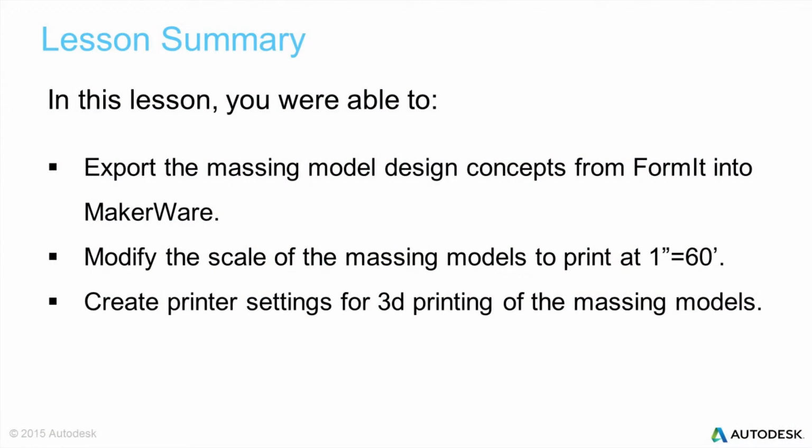So in this video, we learned a couple of key things. We were able to export the massing model design concepts from Format into Makerware. We were able to modify the scale of the massing models to print at 1 inch equals 60 feet. And we were able to create printer settings for 3D printing of the massing models.